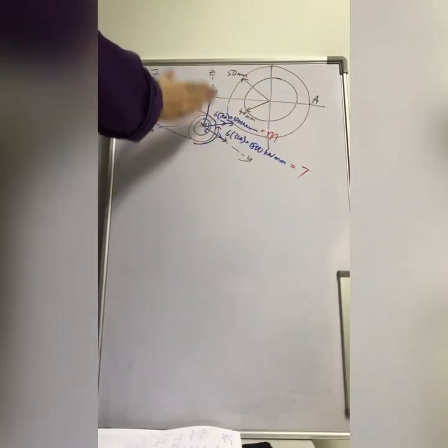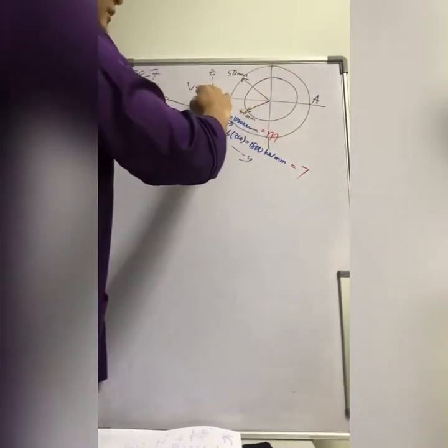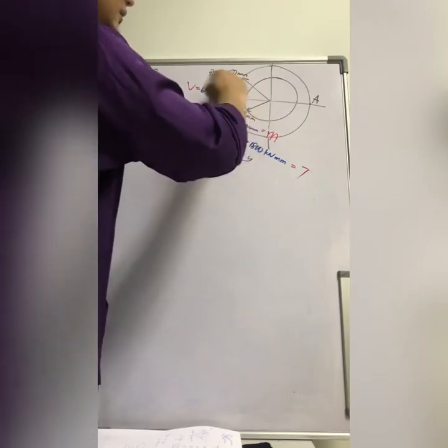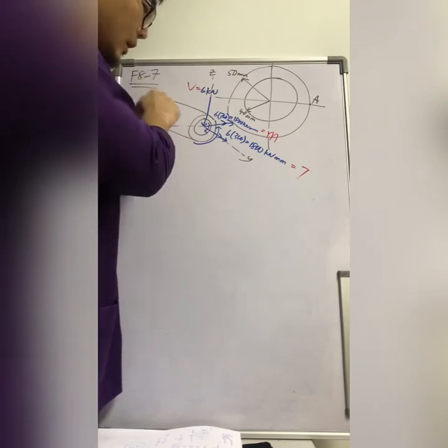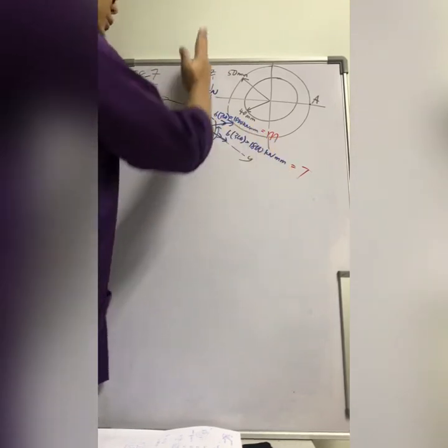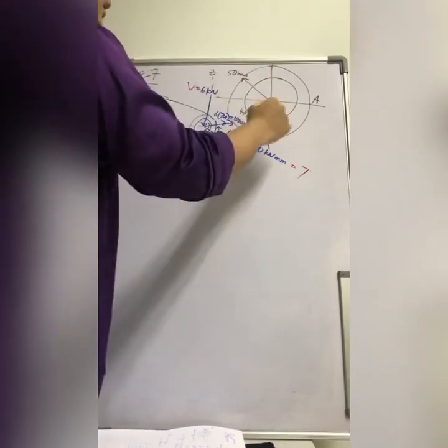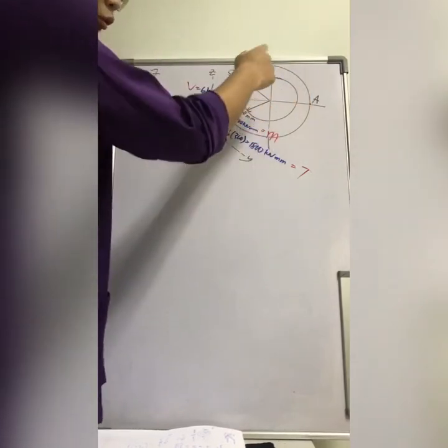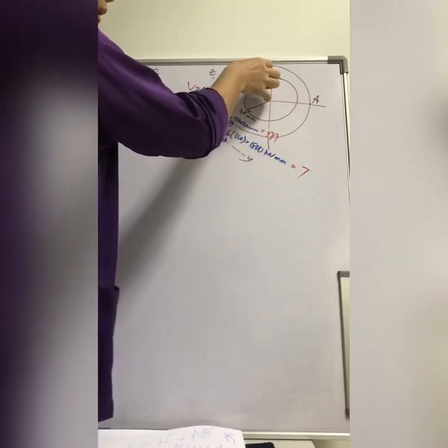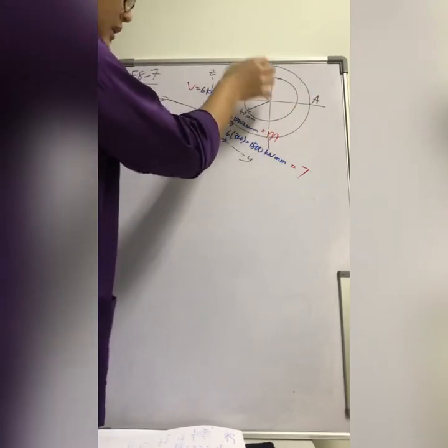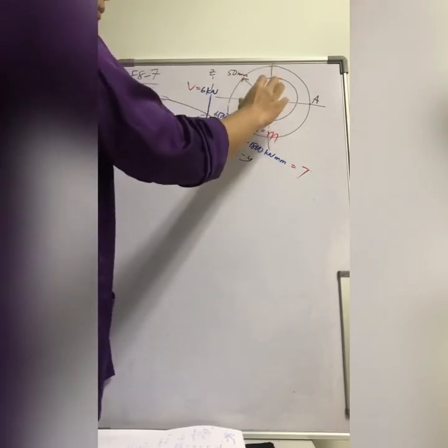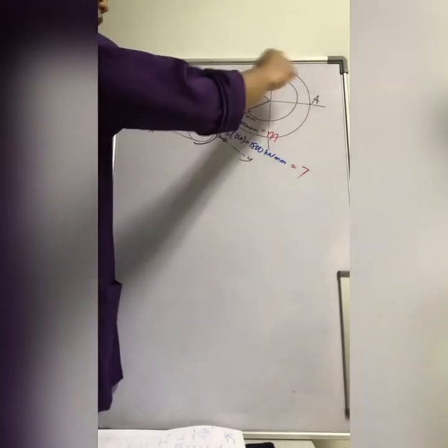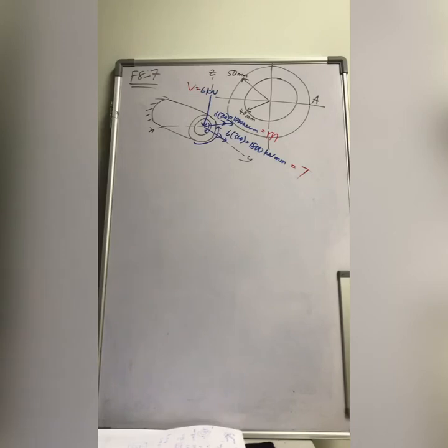And then this cross section is the circular cross section. This is the X axis, this is Y, this is Z. This time around in this configuration, Y is along this pipe, so this one is Z. This is a hollow pipe. The outer radius is 50 millimeter, and the inner radius is 40 millimeter. So you have the hollow diameter of 80 millimeter, and the total diameter is 100 millimeter. Okay, so let's look at the bending stress first.